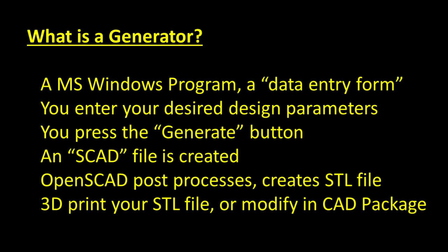Let's get started. So, what is a generator? A generator is a program which runs under Microsoft Windows to allow you to enter your design parameters into a form, push a button, and create an SCAD file containing a 3D model. When this SCAD file is post-processed by a simple program called OpenSCAD, a stereo lithography file is created. The STL file can then be printed directly or modified in a simple CAD program like Tinkercad.